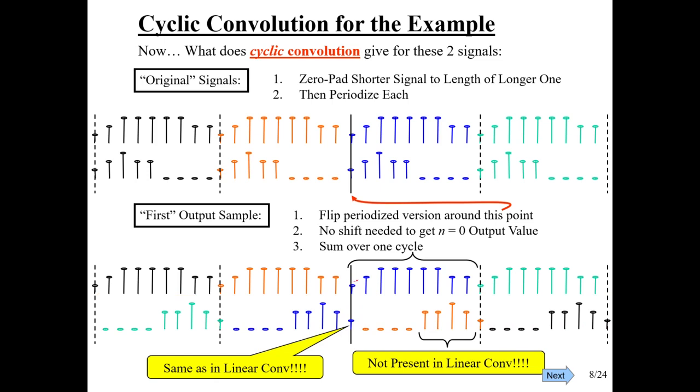And we have it, but we also have all of these products. Oops, not this last one, just these here. We have those, and they were not there. So the answer we get for n equal to 0 for the circular convolution is not the output that we would get for n equal to 0 with a linear convolution, because 4 additional things are being added in.